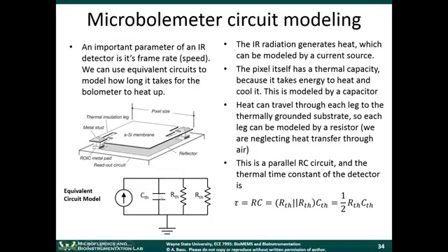Just as a reminder, what is this thermal capacitance? What does it represent physically? Stored energy, that's correct. So stored thermal energy is the fact that the object is hot. Okay, it's going to take some energy to increase the temperature of the object, and also the heat stored in the object can't go away instantaneously. So the temperature of the object can't change instantaneously, just like the voltage across a capacitor cannot change instantaneously. So it's modeled by this capacitance.